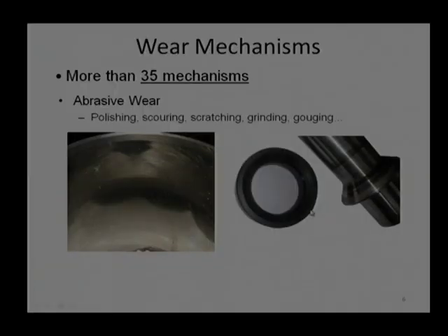I can take a very good example about carbon graphite and stainless steel. We are able to see these black marks on the stainless steel surface. These marks have come directly from carbon powder, and here it has been done intentionally. What we are saying is let carbon graphite transfer its layer onto the stainless steel, because adhesion between stainless steel and carbon graphite is higher compared to cohesion between graphite and graphite. So, a weak interface will be made between graphite and graphite surfaces, but good adhesion will be made between carbon graphite and stainless steel.